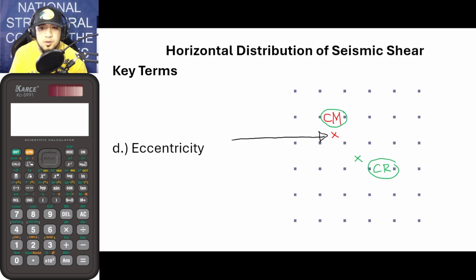So in that case, as you know, the center of rigidity is basically the strongest point on a certain floor, if you take into consideration all of the stiffness. Meaning that is the stiffest point in the floor. And from that, guys, if this is the strongest or stiffest point in a particular floor, there is actually a tendency that the building would twist. Why is that the case? Because we now have an eccentricity. And when we say eccentricity, that is basically the perpendicular distance between the story shear and the center of rigidity. Once again, this is now E.